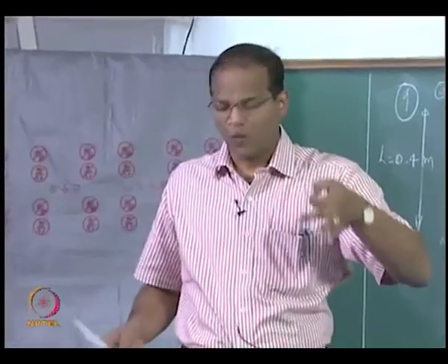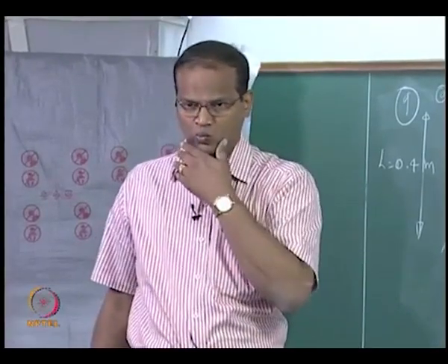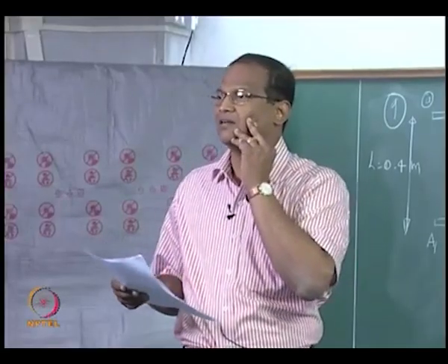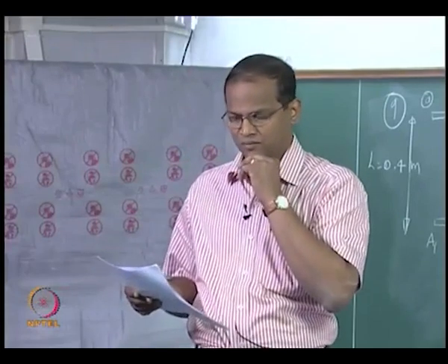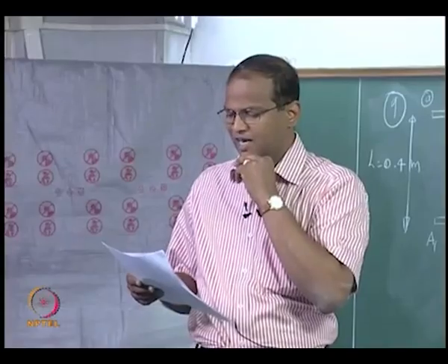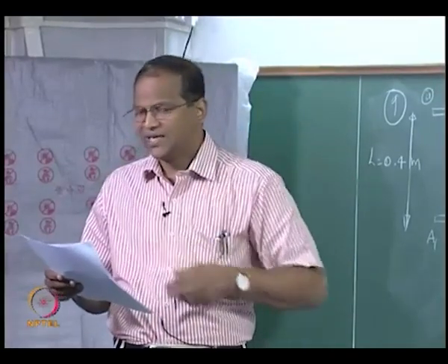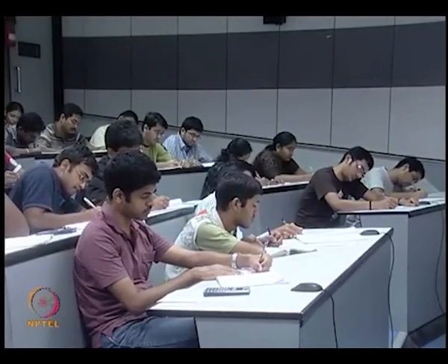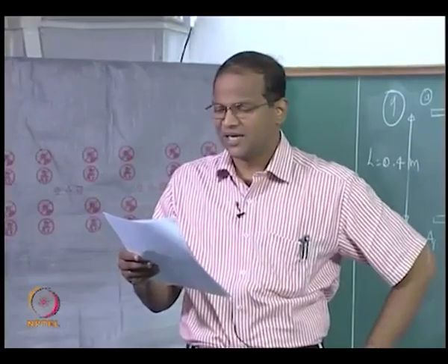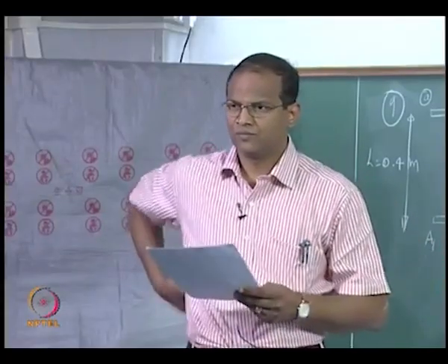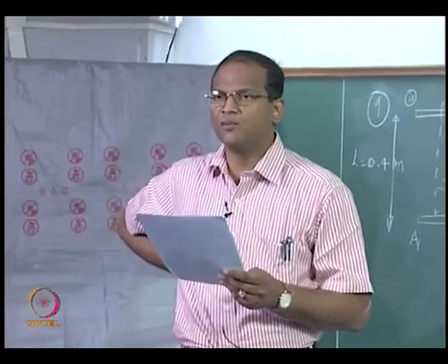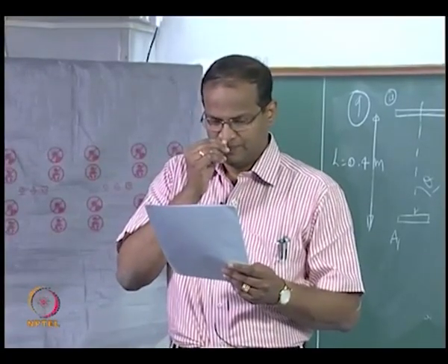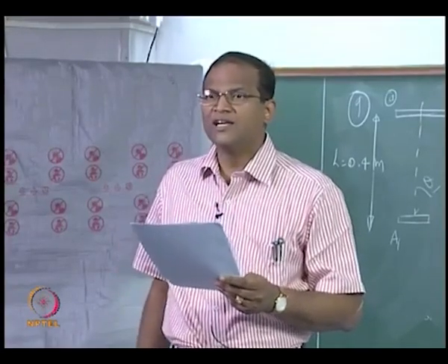For the radiation emitted by A1 at theta equal to 0, within brackets the normal direction, at a distance of L equal to 0.4 meter, the detector measures a radiant power of 1.5 × 10^-6 watts.